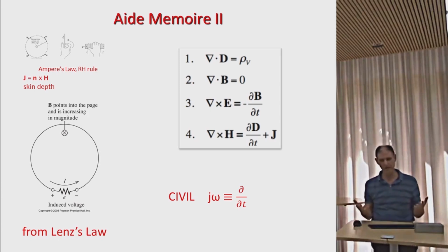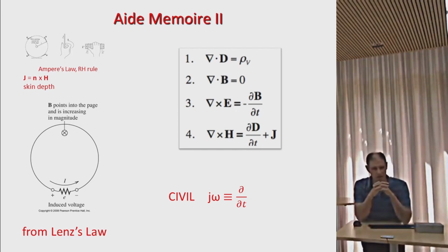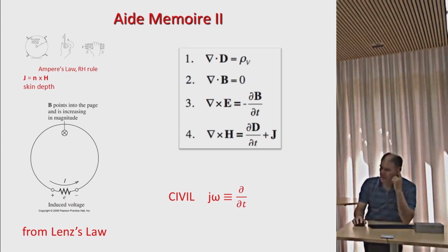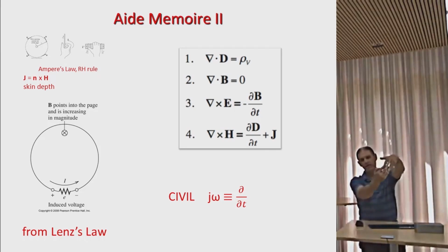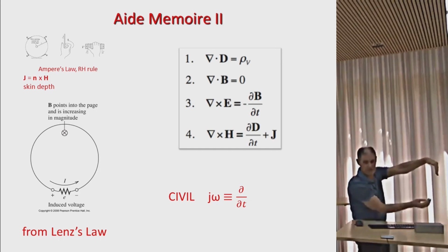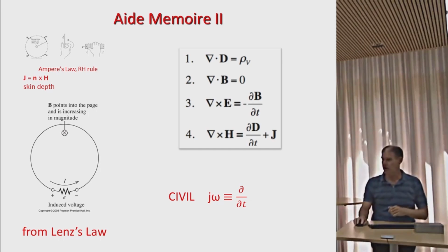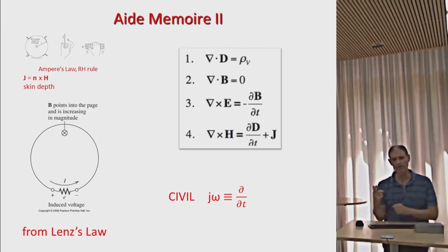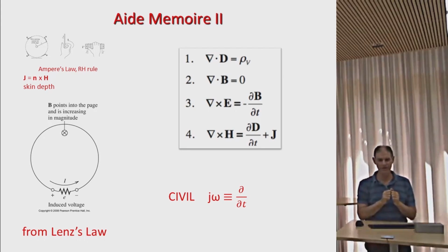I've gone through that quite quickly, but it's a three-dimensional explanation noted by Maxwell, telling us how waves propagate in space and how they couple into media. The loop underneath here, Lenz's law, is also quite interesting. If you have a loop of wire, so you've got an experiment and you create a loop of wire, if there's any magnetic field which cuts that wire, it will cause an induced voltage which causes current to flow in the loop which tries to oppose the field which creates it.